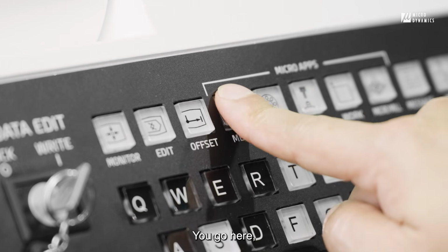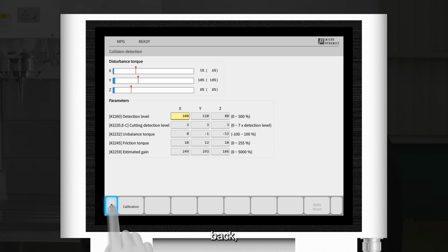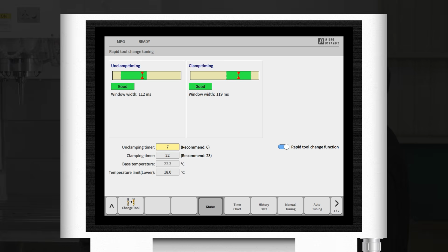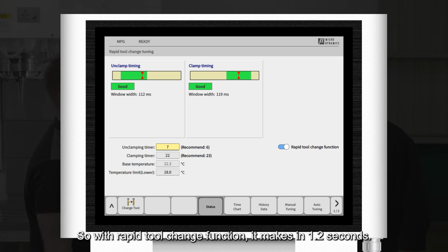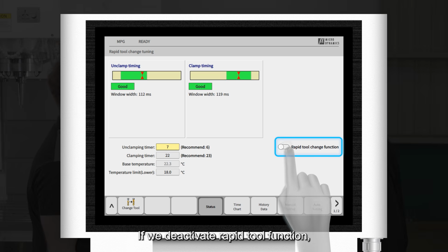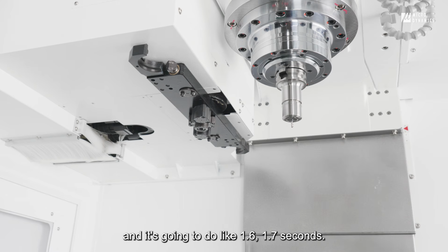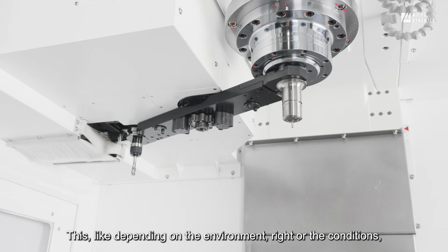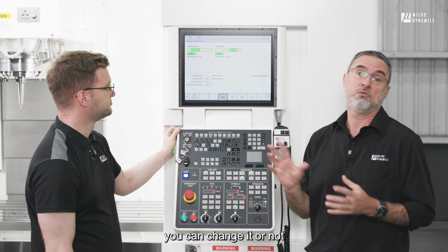Yes, you go here to the servo tune, back, rapid TC tune, and here you can turn off this function. So with the rapid tool change function, it makes it in 1.2 seconds. If we deactivate the rapid tool function, it's going to stop under the arm and it's going to take like 1.6, 1.7 seconds. Depending on the environment or the conditions, you can change it or not.